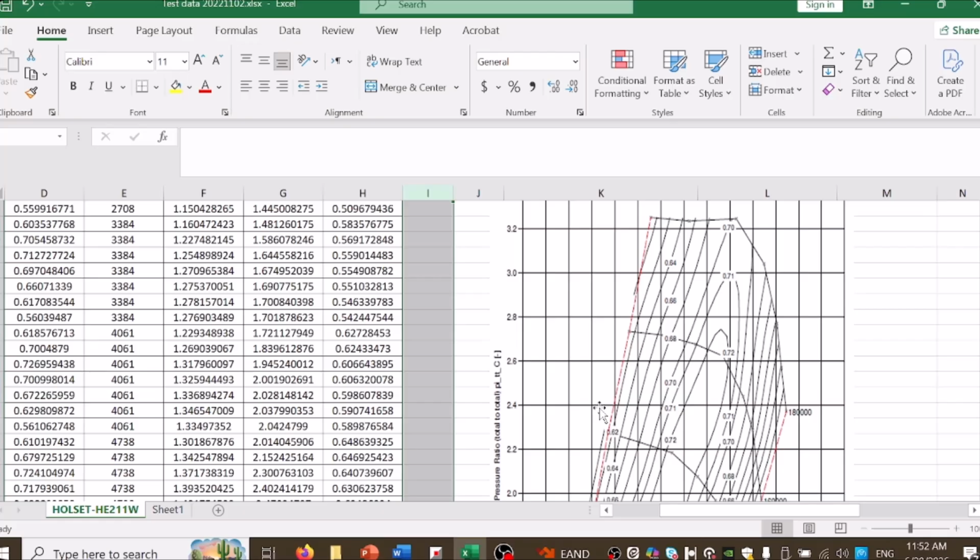This causes unstable flow and air can momentarily reverse direction. Symptoms are a fluttering or puffing sound, vibration, poor compressor stability, possible damage over time. In simple terms, too much pressure demand with too little airflow is called surge.